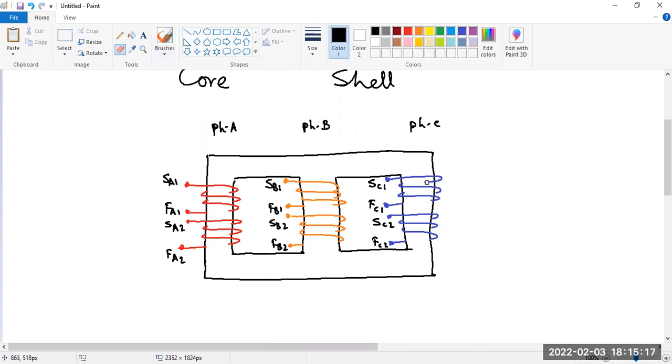Sir, you were asking about power lines, the overhead towers. Yes, power line. Three phase. It can be three phase three wire or three phase four wire. In case of three wire, there will be three cable lines, and in four wire there will be an additional neutral line. So four lines, four wires you get.